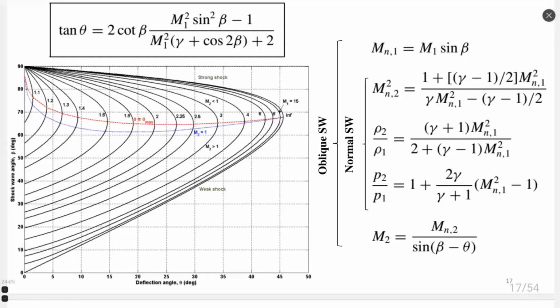So he shows that there are two solutions. The so-called weak shock solution is what we are looking for. And there is another, the strong shock, that we are not looking for because it does not happen. But this equation has two roots, because if we analyze this equation, it has Mach squared, so definitely it's a parabolic function. And this parabolic function usually has two roots. Any parabola has two roots. So this is this case. Strong shock we are not looking for.